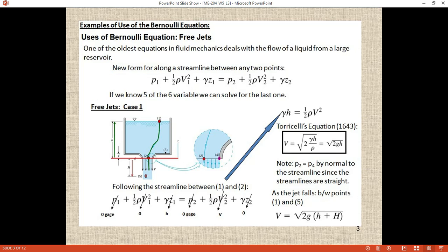Now the third assumption: at point 1 at the top of the reservoir, since the reservoir is too big, when the water level or fluid level reduces, it will be very hard to observe. The velocity will be very low, because there is a large surface, so when the fluid comes out from a small outlet, the top surface will move very slowly.